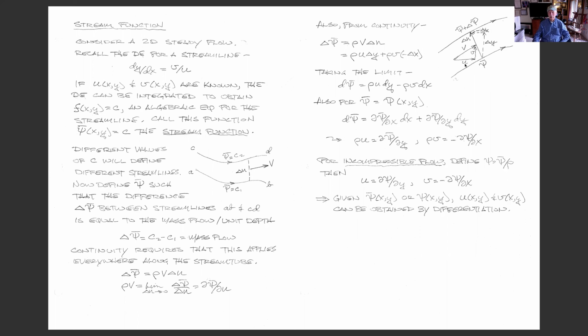And we said this is supposed to be the mass flow. Well, little u is carrying mass across this delta y. And little v is carrying this flow across minus delta x. So it seems a crude, cumbersome way to write this, but hang on. We get rho u delta y plus rho v times minus delta x represents delta psi, the mass flow.